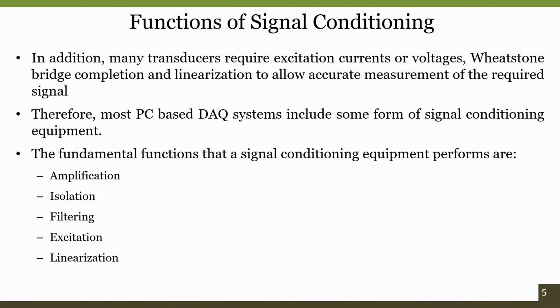So when I briefly describe the fundamental functions, one advantage of having signal conditioning is amplification. So you can have amplification, isolation between your input stage and the output stage. When the recorded signal has noise, the signal conditioning system should have the ability to filter out the noise and extract the useful information from the actual data.